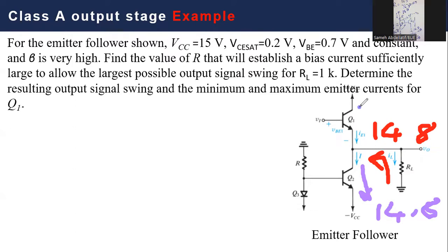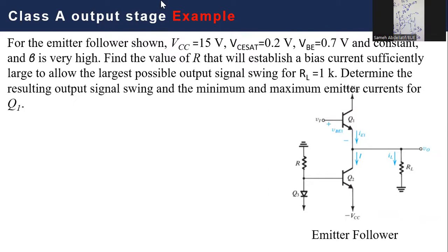Resulting that this Q1 at this stage has 0 current, or basically it's turned off at this point. So the maximum current flowing in Q1 is 2 or double the current flowing in the current source, which is in our case 29.6 milliampere, and the minimum current flowing in this Q1 is typically 0. This is, I think, all we need to answer this important question.